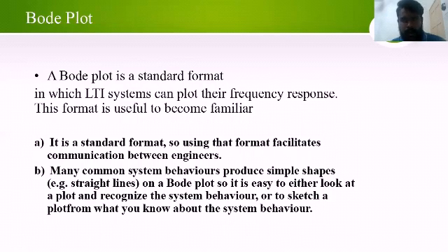And besides root locus, the Bode plot is also the main standard format in which an LTI system can plot its frequency response, using a standard format that facilitates communication between engineers. Besides, common system behaviors produce simple shapes such as straight lines, and the Bode plot makes it easy to look at the plot and recognize the system behavior.